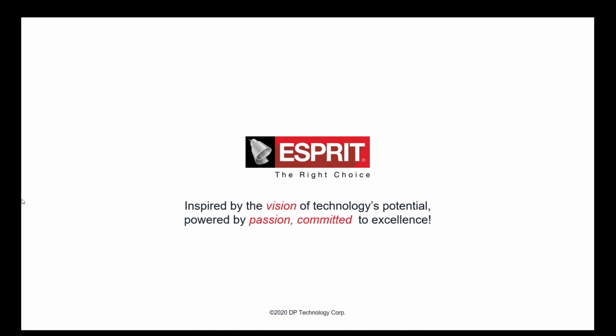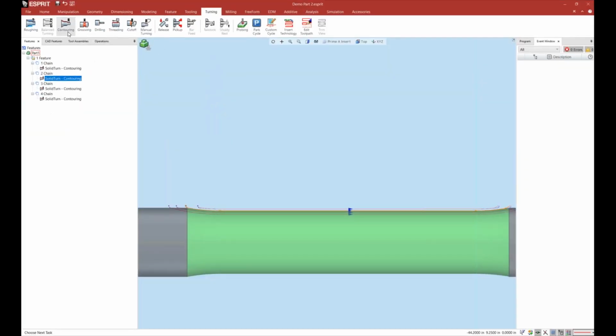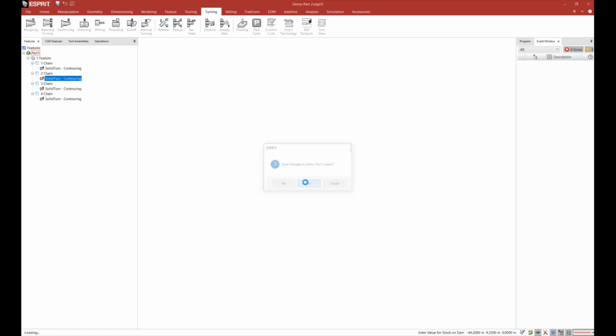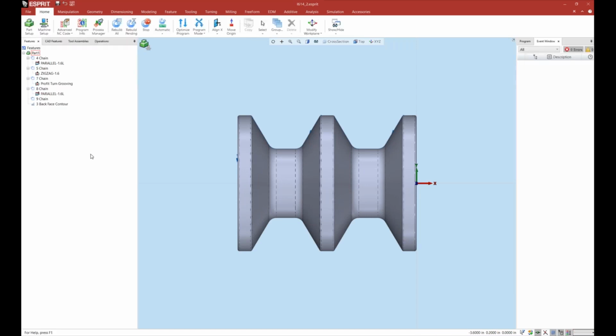Okay. So, Kevin, somebody was asking if they could see the tool definition for that Y-axis cutoff tool. We were just creating a regular grooving tool, and then we imported the holders that were given to us by Sandvik. Those tool holders are on our website. You can download those models off the Sandvik Coromant website.